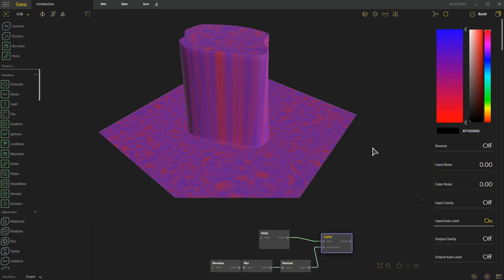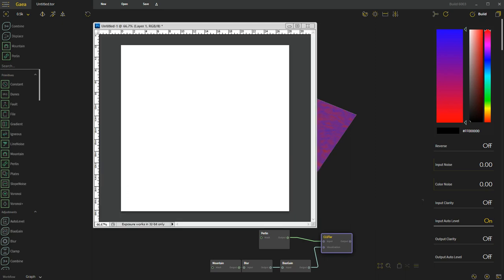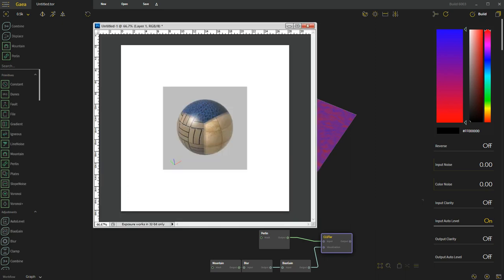if you've been using Gaea for a while, you may remember there was some textured shaders that were applied, and they were a bit of a misleading kind of effect because they had what was called triplanar mapping on them. So triplanar mapping is basically taking any kind of surface and creating a series of projections at different angles. So faces facing in that direction are not really showing the texture that this is. They're showing like screen projectors, where they're projecting onto only flat surfaces based on the angle that they're projecting through.